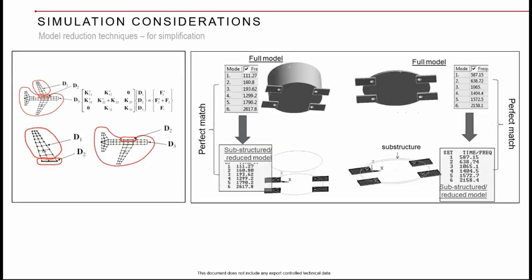Okay. So again, these are some simulation considerations which I'll quickly walk through. Like the previous case, we have seen a flexible member, which you cannot model as a point mass, but still you can consider some other methods when you want to simplify bigger structures like this with both stiffness and mass. Model reduction techniques such as substructuring or super element analysis we call, or reduced order modeling also you can call. All these kinds of techniques you can adopt and you can represent the mass which is not of your interest, but you want to capture it adequately.